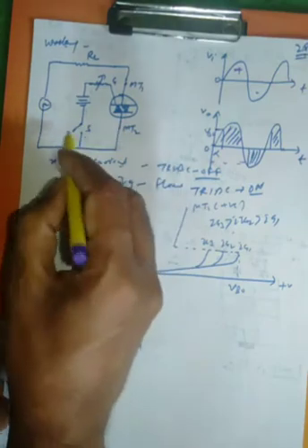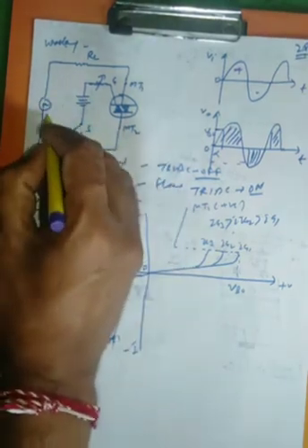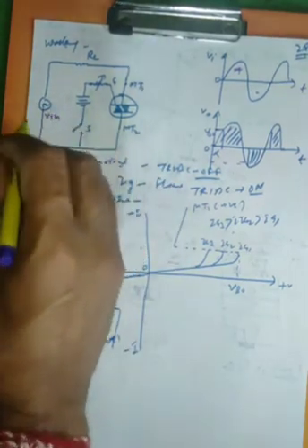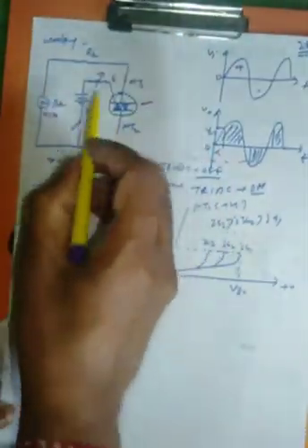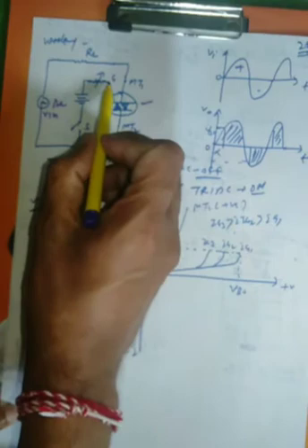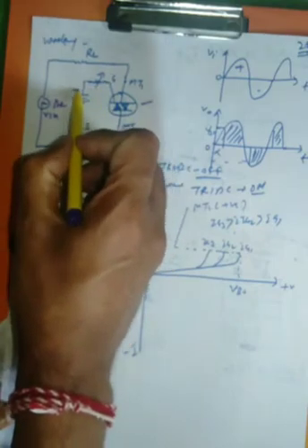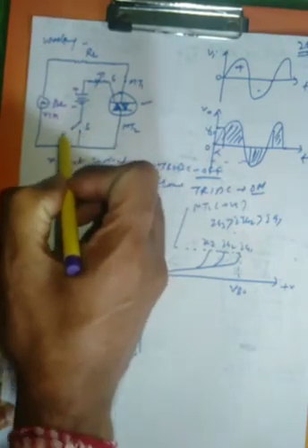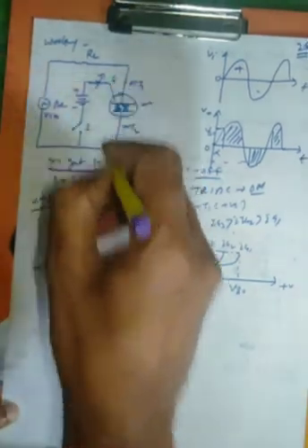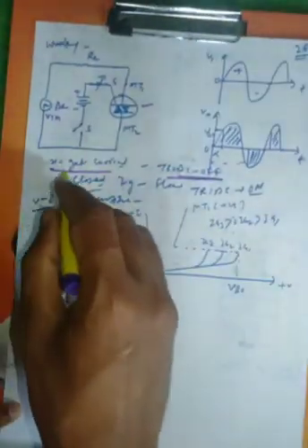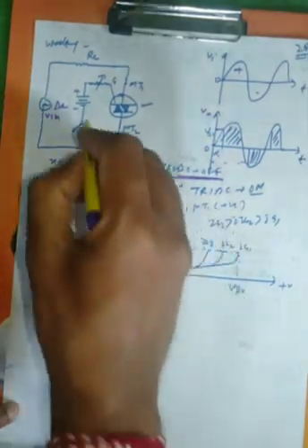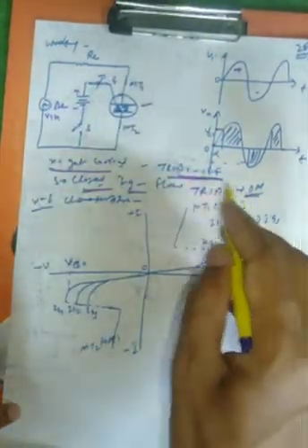This is the circuit diagram. You can see the AC input is applied here, and then there is a load resistance, then this is the Triac, and the gate is common to both, then there is a resistance, then the supply voltage, then a switch, which is open. If no gate current is applied to the Triac, then the Triac will be in the off state. When S is closed, then gate current will flow through the Triac and it will be in the on state.